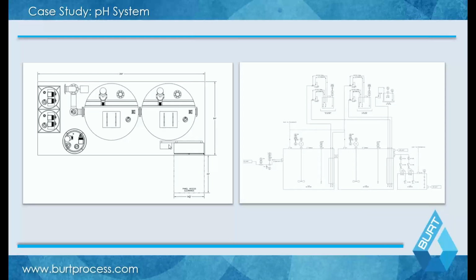Two 800-gallon tanks, a control-based system with panel access, your reagent injections. In this case, you have your buffer addition as well for your high purity water. The system gets fairly big, 200 inches by 7 feet. So you have a lot of tank volume going on in your system, which is why it's important to understand what your flow profile is and not undersize it.